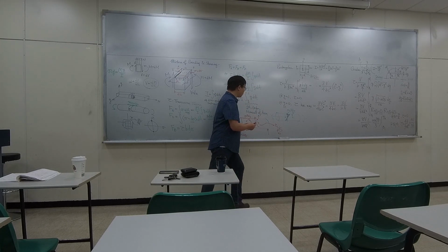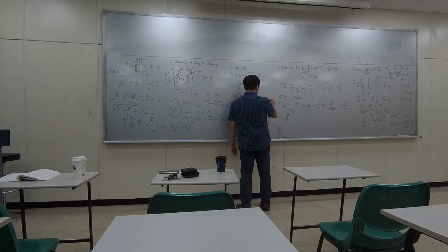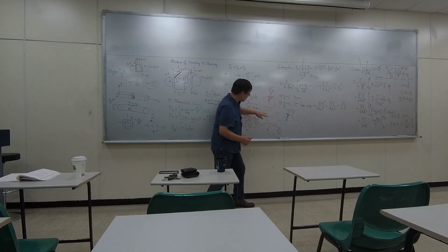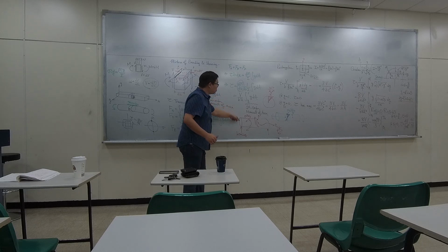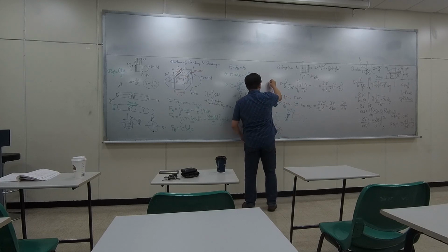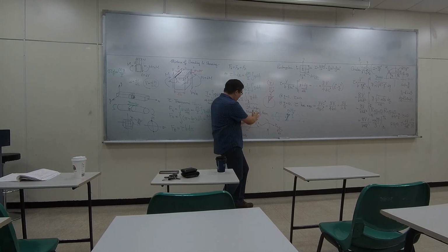That shearing force looks like this when you look at the cross section. So it's like this, shearing stress. And this is 16T over pi d cubed, okay? So the shear is everywhere. Now, in this problem, we also have bending moment. So this is one phenomenon we need to deal with everywhere.